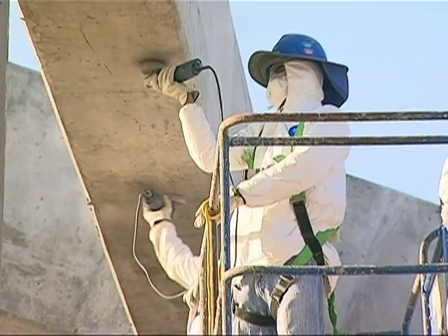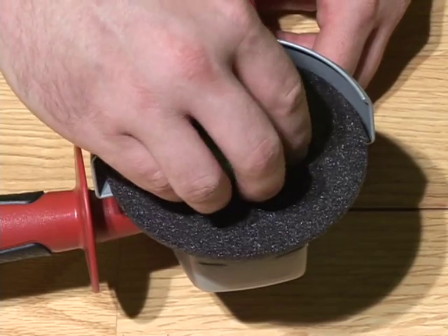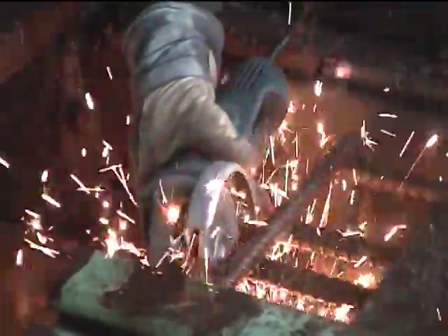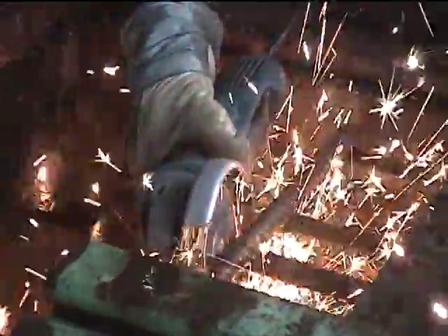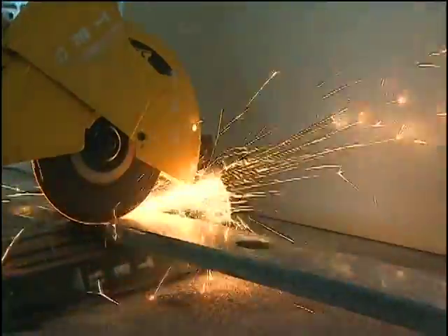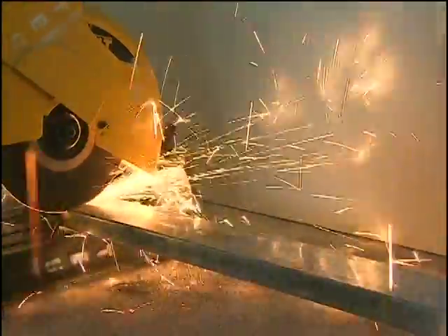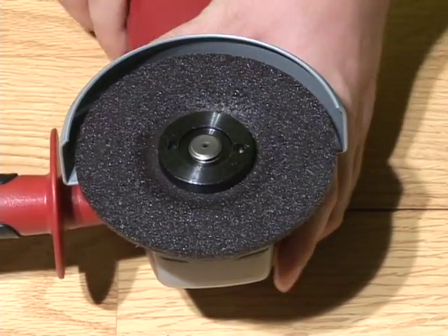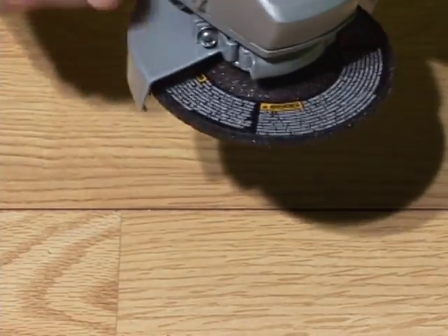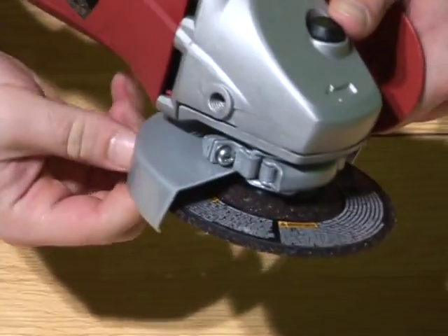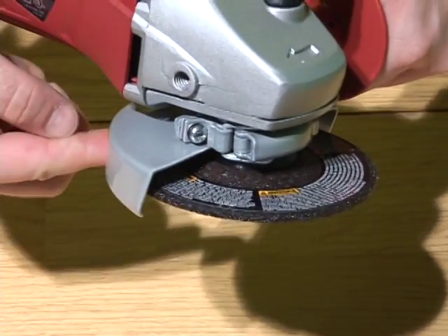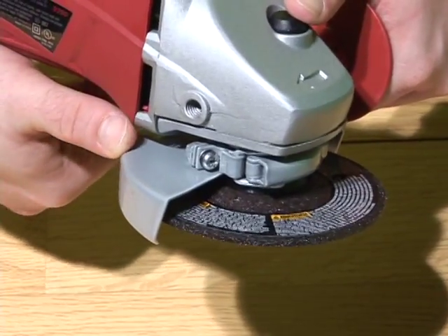Portable abrasive grinding, cutting, polishing, and wire buffing wheels create special safety problems because they may throw off flying fragments and sparks depending on the grinding surface. These tools can be either electric or pneumatic. Abrasive wheel tools must be equipped with guards that cover the spindle end, nut and flange projections while maintaining proper alignment with the wheel. The guard cannot exceed the strength of the fastenings.